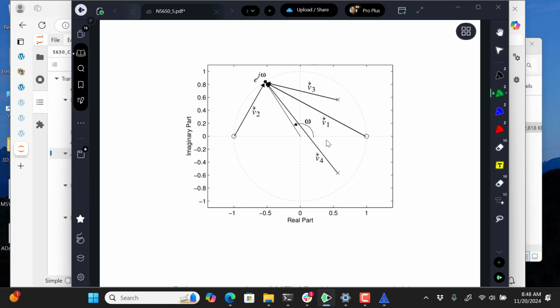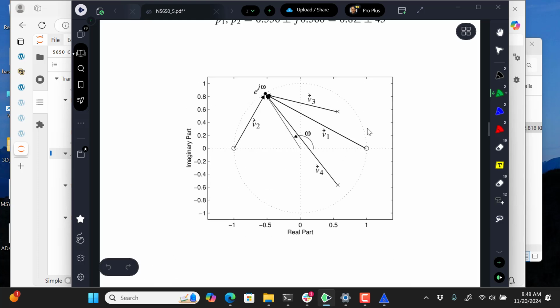And the geometry intuition on this one is pretty nice, because it says that if you wanted to build a very minimal bandpass filter, you would for sure say, I don't want to pass at DC, and I don't want to pass at pi, but I'll put this conjugate pair of poles up, and I can control the radius of these poles, and then as I cruise around and go past that guy, I will peak up and get a nice response.